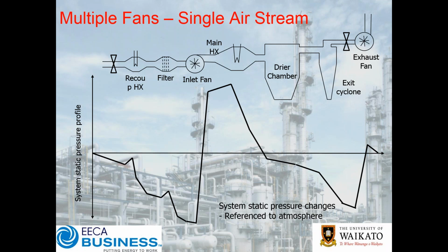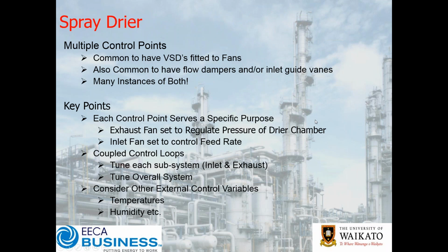And so what you'll have in your system is multiple variables all being controlled by separate systems that may be coupled, or they could be quite independent. Now, of course, what happens as you increase a feed of airflow, assuming you've got a heat exchanger and you're controlling to a temperature, you're going to change the energy going in.